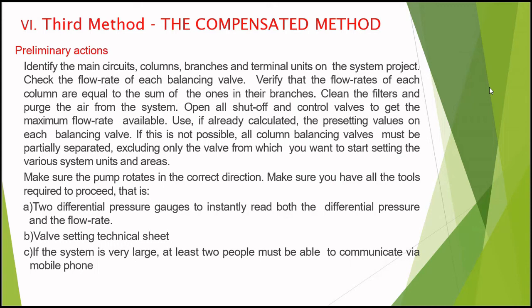If this is not possible, all column balancing valves must be partially closed, excluding only the valve from which you want to start setting the various system units and areas.